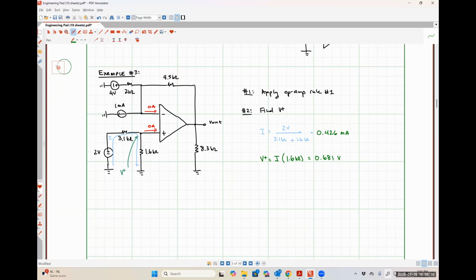So, and again, this is based off of West's observation. If there's no current that is allowed to flow to the right through into the input terminal, then, and Jaime just nailed it, we can just treat these resistors as if they are in series and use voltage division. Okay, so Jaime is absolutely correct.